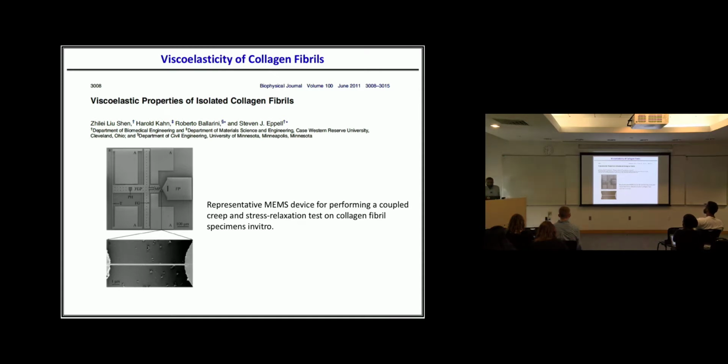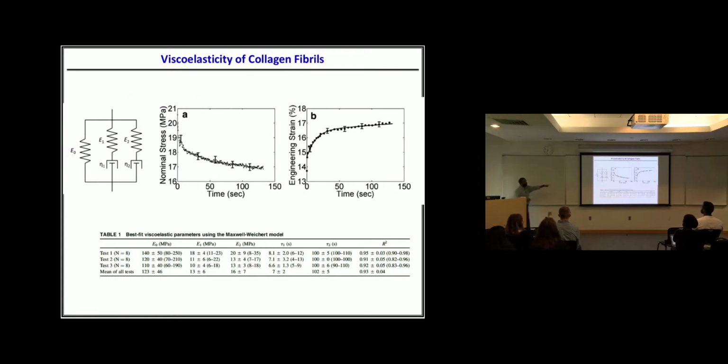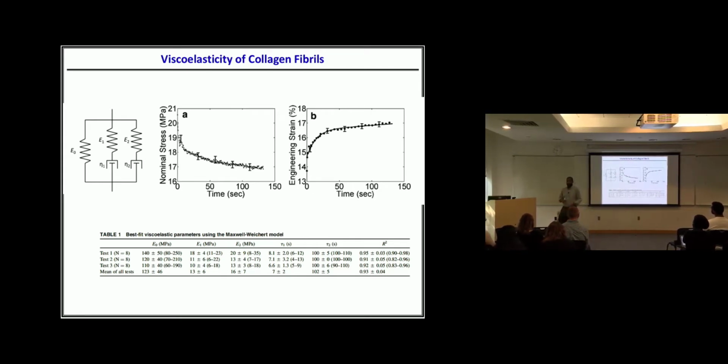And if you do that, basically what you get is this. You see exactly this stress relaxation, and then you see creep. The material is deforming more and more. When I told you about that one crosslink, there was one time scale, but there could be multiple crosslinks: one kind of crosslink, a second kind of crosslink. Each of them will have its own time constant.